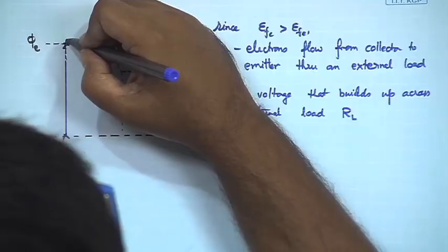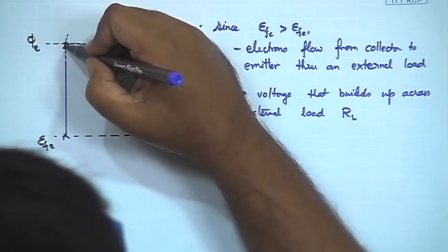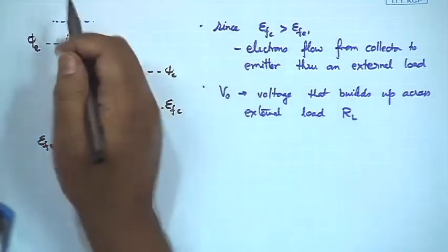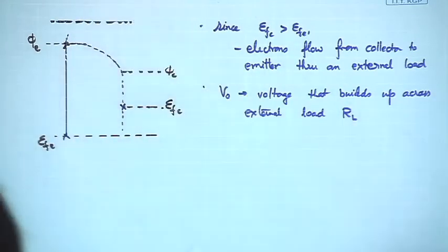Okay. So, these two actually oppose the thermionic generation, the build up of the voltage of the thermionic generation or the current flow. So, just having that energy level at the work function of the emitter may be okay to initiate the thermionic generation, but to sustain it, it is not going to be enough. So, in reality, we are going to need the energy level to go higher than just the work function.